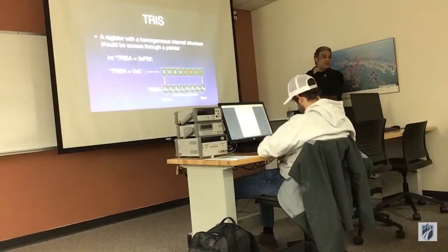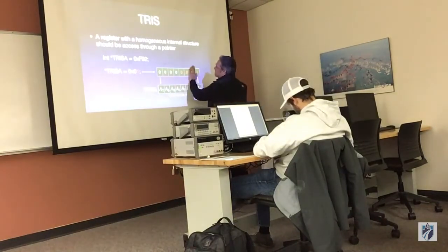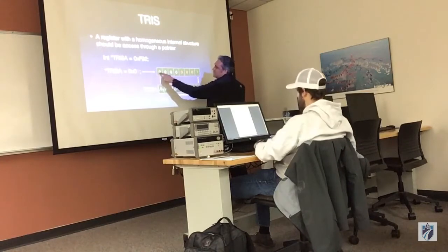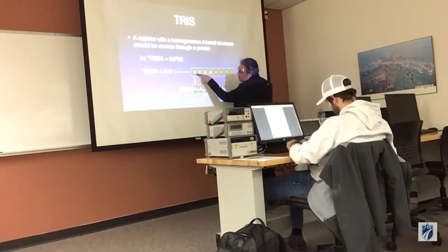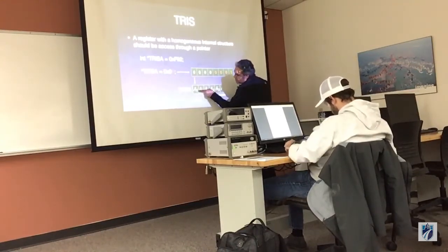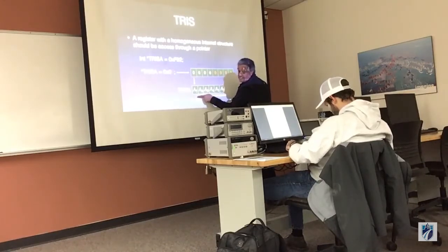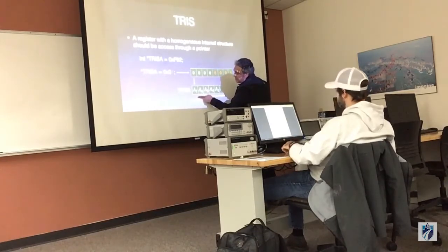It becomes an input. See that? The same thing is happening on that 0. Now, I'm not talking about the guys in the middle because by explaining that 0, we know what the rest of the pins are doing. But the moment that that 0 lands in that position, it's going to force pin 7, A7, which is physical pin 13, to now behave as an output.